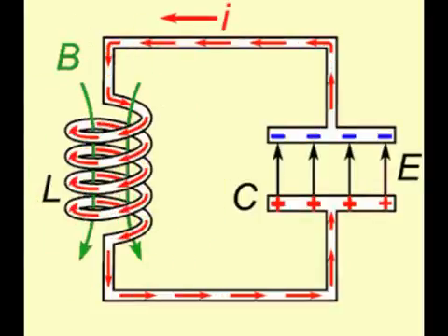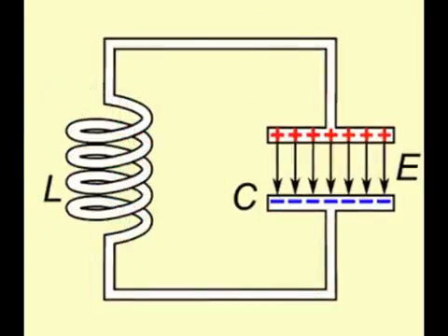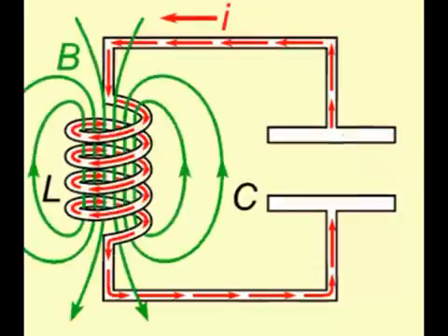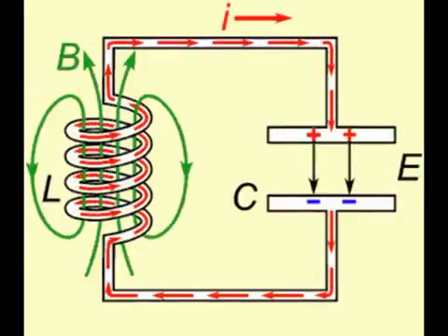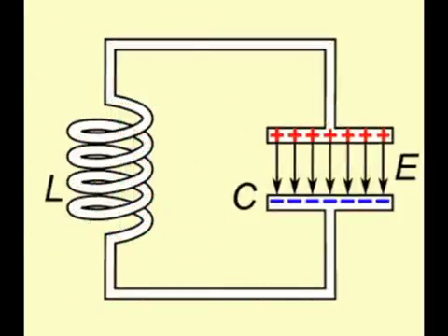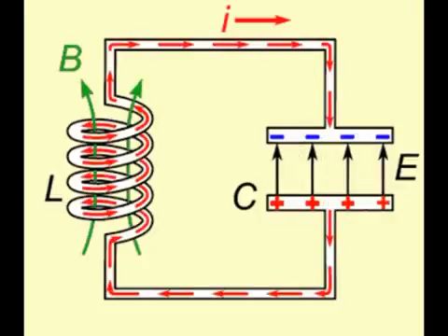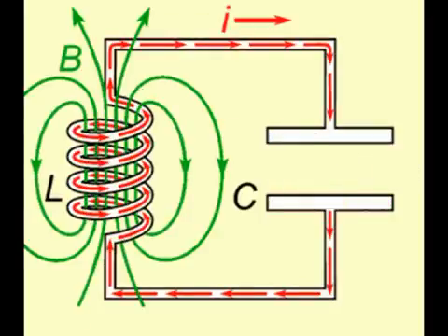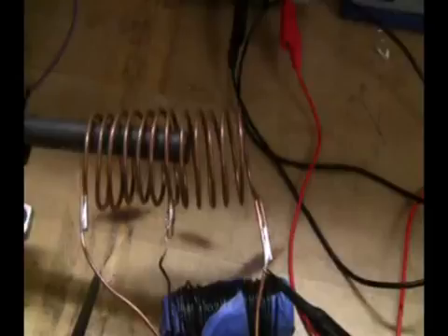The resonator is technically an LC circuit. This means that charge is built up in the capacitor then discharged, which induces a current into the inductor. The inductor then stores the energy. The LC circuit oscillates. The devices charge and discharge each other. The frequency created by the AC waveform is the resonant frequency. This means that the total impedance should be zero. When a conductive or magnetic object is placed inside the inductor coil, an inductive link is formed. This causes an energy transfer from the tank resonator subsystem to the object.